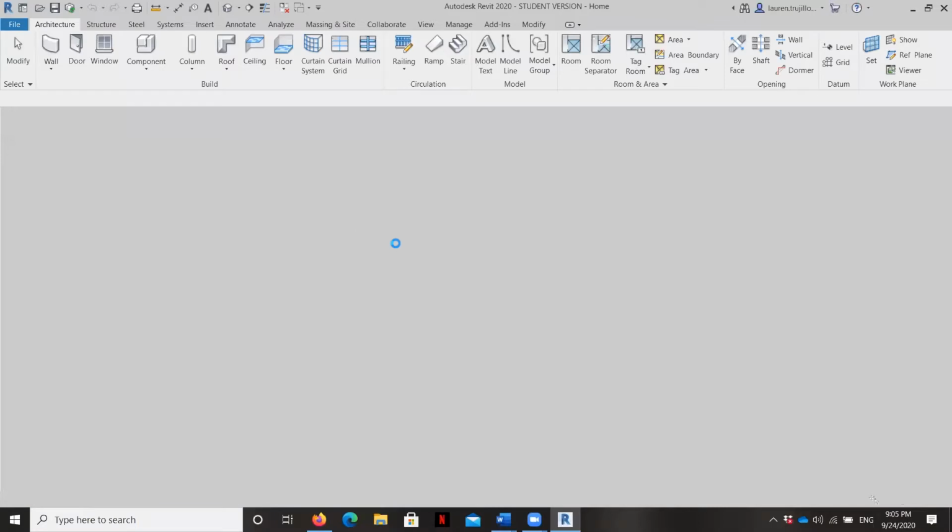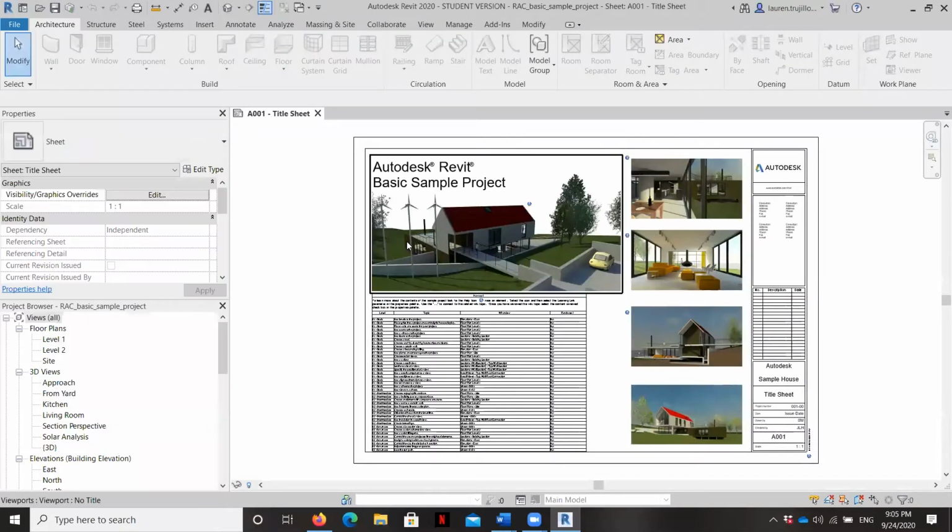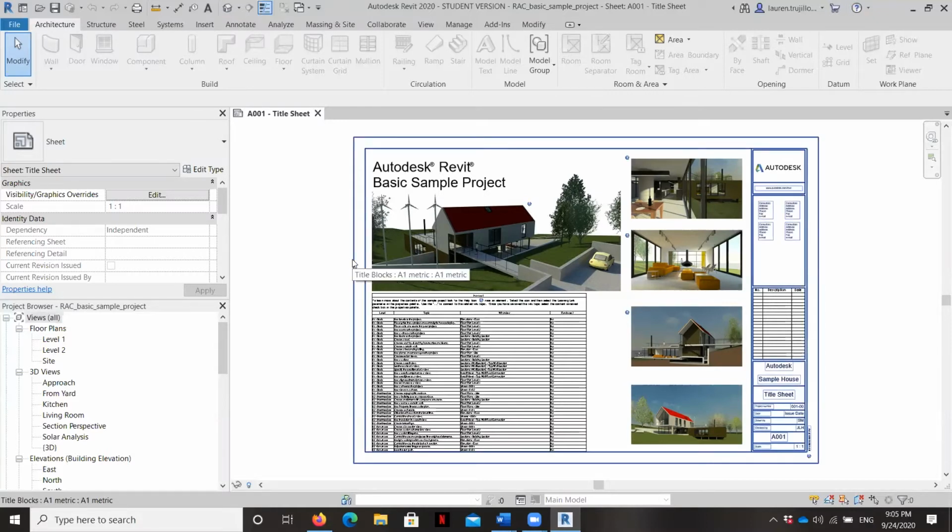And so the first thing that I want you to realize as you're operating Revit is that Revit depends on the designer to create a model. And so you might hear me use the term drawing, but really I'm going to try my hardest to refer to this as a Revit model, because this is really almost like a physical model that you can hold in your hand. And so Revit has the designer create this three-dimensional thing, this model, and then the designer decides what views they want the viewer to see, and then dictates that on the actual model.